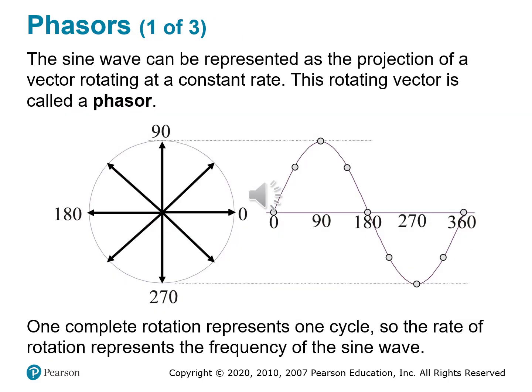All right, let's continue on with phasors, sine waves that spin. I have a nice animation for this, and I'll show this to you in class. This still image doesn't do it justice. So you've seen sine waves drawn across time, but what if I told you that sine waves can also be visualized as something rotating? And that's the concept behind phasors. A phasor is a rotating vector that traces out a sine wave as it spins around a circle at a constant rate.